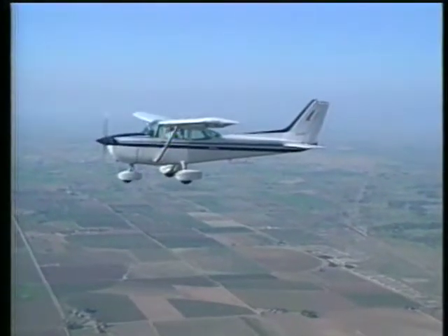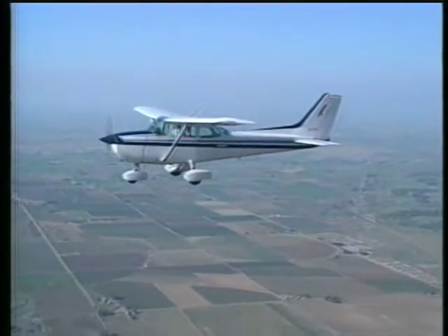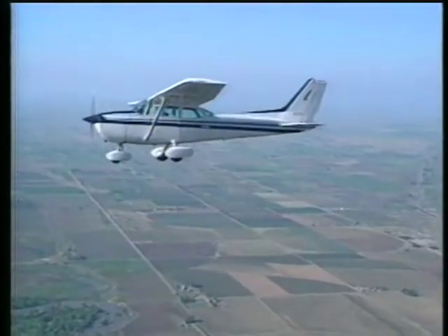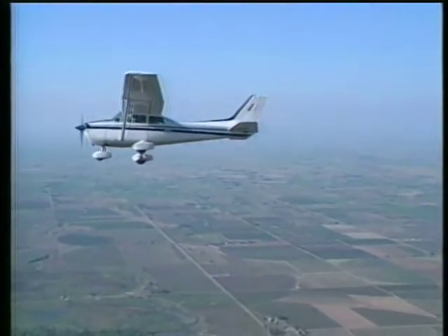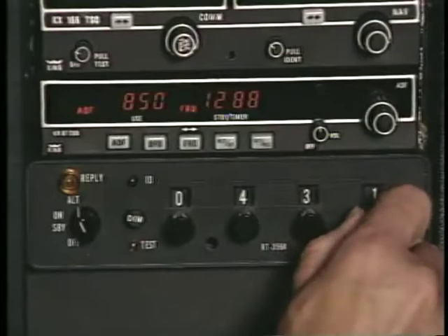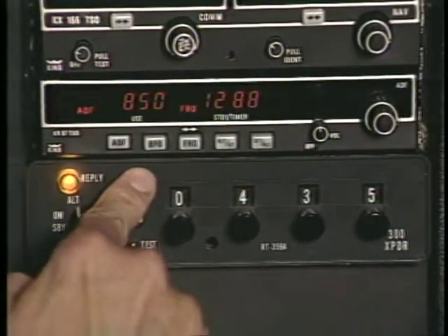Cessna 740, stand by. Since the controller used your call sign, radio communications have been established. This means you can continue on course and enter the Class C airspace. If the controller uses the words, Aircraft calling Jensen approach, stand by, radio communications have not been established, and you must remain clear of the Class C airspace. In most cases, the controller will give you a transponder code and ask you to ident. Cessna 740, radar contact, 23 miles northeast of Jensen, turn left, heading 220 for left base, runway 17.